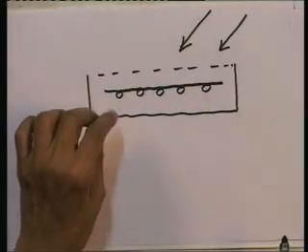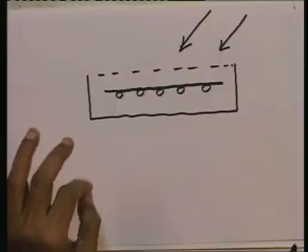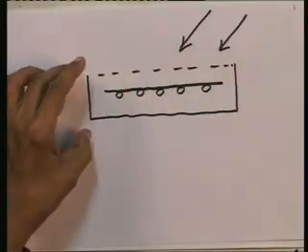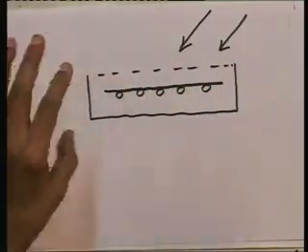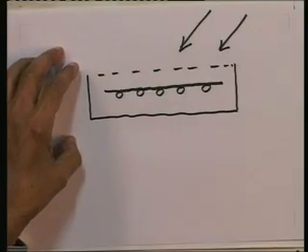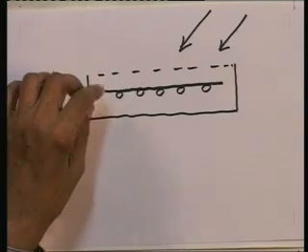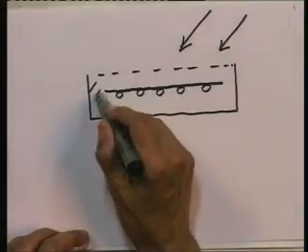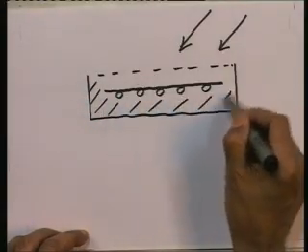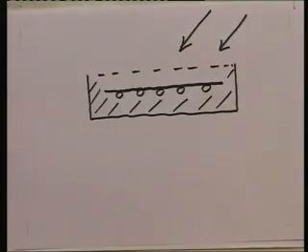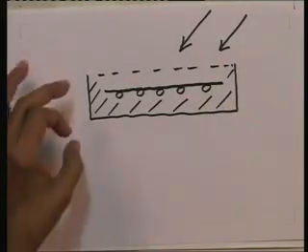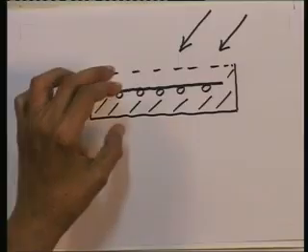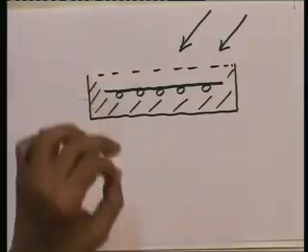Now, today we will stop here, but next time I will look at the different modes of heat transfer that are occurring in this device. So, we will take off from this point in the next lecture. We have described a solar flat plate collector. You know what are the components that make it up: an absorber plate, tubes, a glass cover on top, and on the back side here there is insulation to prevent heat loss to the sides and the bottom. These are the components that make up the flat plate collector. Next time, in the next lecture, we will look at the different modes of heat transfer that occur within this device and write down a simple energy balance equation for it.